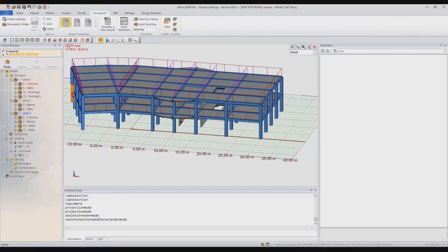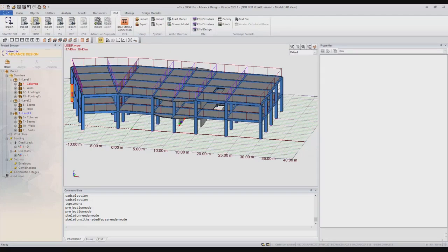In Documents is some tools to help you generate documents. So we have templates that we've created for you. The BIM tab is all of the import-export. If you're working with Advanced Steel or Revit, it's better to use the GRAITEC format so it would transfer more information. It's a lot faster. But if you need to communicate with other software, you can use the IFC, SDNF, SIS2, PSS, or DXF format. We also have a direct link with EDS-ICA, so you can send the geometry and the analysis result for a connection.